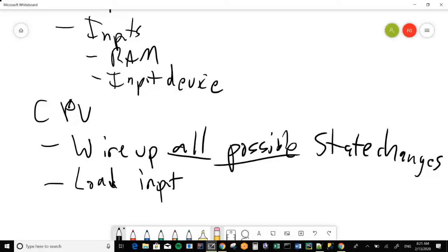And we saw examples of that last time when we were considering the distinction between an A instruction and a C instruction. With a C instruction, different bits enable different things to happen. With an A instruction, you're just loading an address. Well, if you're not careful to suppress the load bits when an A instruction happens, just loading an address can cause all kinds of bizarre state changes. So the load input, getting the load inputs right on your state elements is essential for building a CPU.